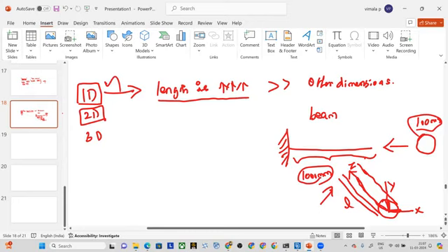Instead, if you regard that as 1D and do the mesh, you can finish it off in seconds. And if you solve, immediately the answer will pop up. But both cases will give you the same answer. That is the beauty. Which means you should be able to understand what is a 1D component: all those which have the length very, very large when compared to the other dimensions. I have given a beam as an example. You can even consider columns, right?